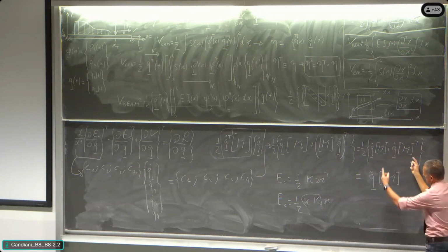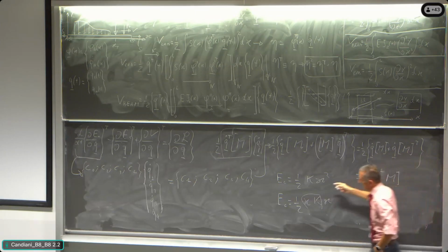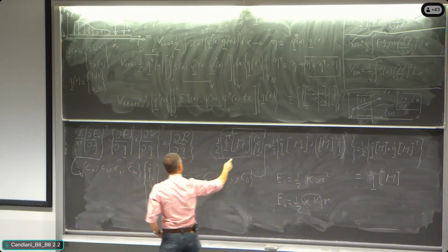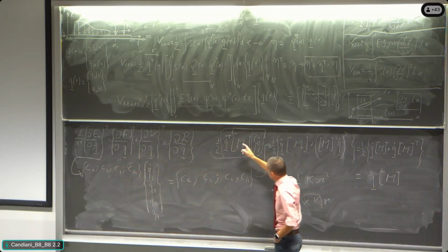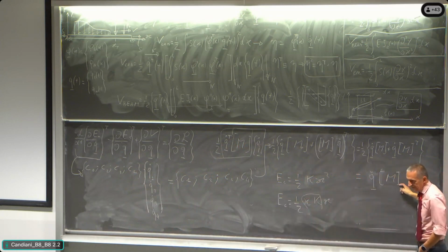And so you can say that the derivative with respect of the vector q dot of the quantity 1/2 q dot transpose M q dot is actually q dot mass matrix, in case it is symmetrical.